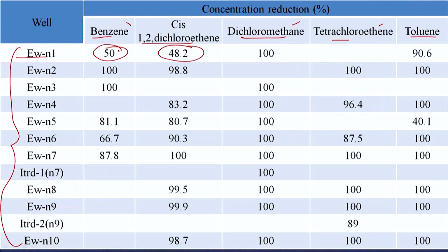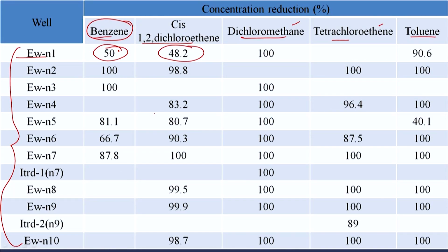If your contaminant is present as an NAPL, or as benzene itself or 1,2-DCE itself, or you have an NAPL phase, or if you have considerable fractions adsorbed onto the relevant soil. The compound can also change phase from the water into the gas, or if it is very hydrophobic, it wants to be adsorbed onto the soil. In such a case, even though you are going to have desorption from the soil, depending on the kinetics or the octanol-water partitioning coefficient, you might not have complete removal, because here we are only trying to pump out the relevant air.